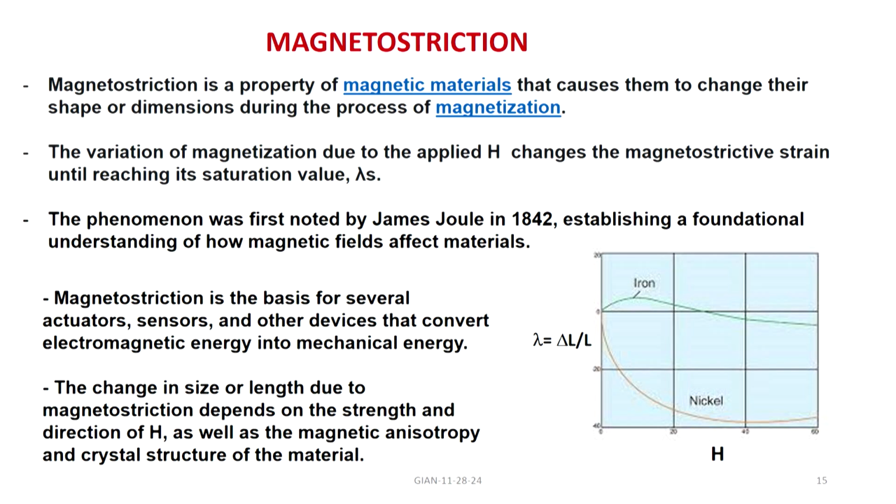Cobalt has positive magnetostriction, nickel has negative, manganese ferrite has positive, and the lead glass that we saw earlier has positive magnetostriction. So, there is nothing unique about whether it can be positive or negative, it could be either one depending on the nature of the material, but the driving mechanism is the rotation and expansion of the domains in the ferromagnet under an external magnetic field.